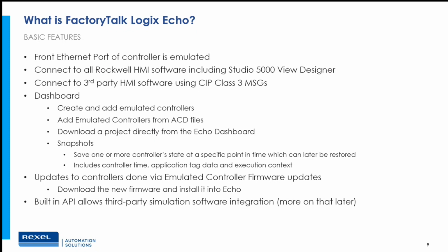Another feature of Logix Echo: you can do snapshots. If you have one or more controllers open, maybe with a program in each one, and maybe they're interacting with each other, you could take a snapshot of all of those together or just one of them. It'll save the controller state, controller time, tag data, and execution context. You can save it as a single file, and then bring it back in and restore it later and take off right where you left off before.